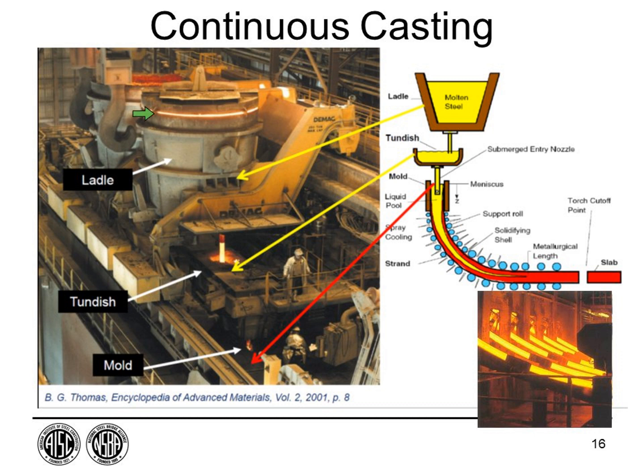It had the chemistry adjusted and the final steel. And at the bottom of the ladle this liquid steel comes out, and this is shown schematically coming down here. It goes into something called the tundish, which is just a bath here to contain that steel. And then it exits the tundish down into this mold.